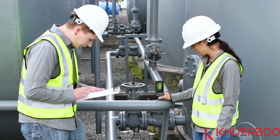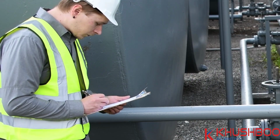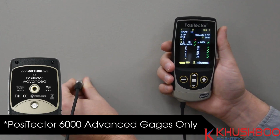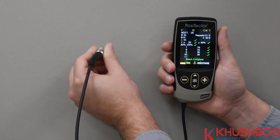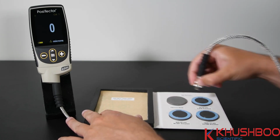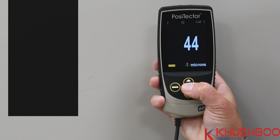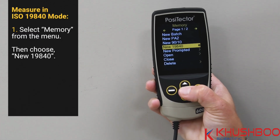Performed manually, the process can be confusing and requires several manual calculations. Using the ISO 19840 mode included with the PosiTector 6000 advanced models, an ISO 19840 inspection is easy. First, ensure that the instrument is verified and adjusted for the substrate geometry. Once the instrument is ready to measure, select Memory from the Gauge menu and choose New 19840.